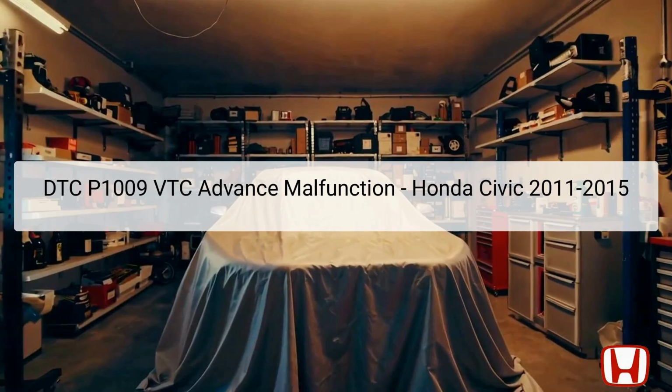This issue can manifest through various symptoms, including reduced engine power or unusual engine noises. It's important to note that this code must be addressed promptly to prevent further engine damage or performance issues. The troubleshooting process involves several steps, including visual checks and operational tests, which are methodical and designed to isolate the problem effectively. Key components involved in this troubleshooting include the VTC strainer, oil control solenoid valve, and actuator, which are integral to the VTC system's functionality.